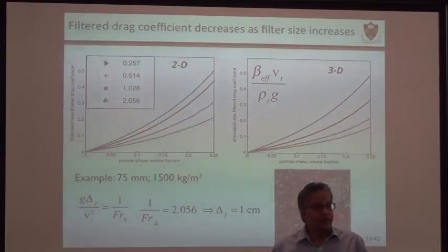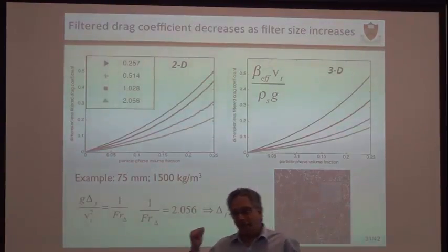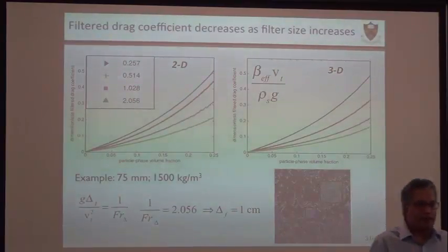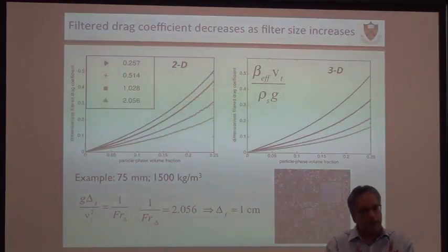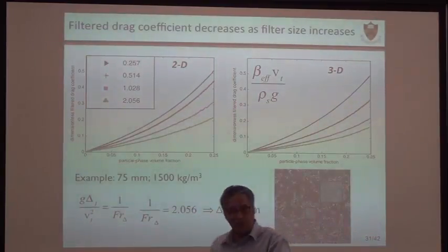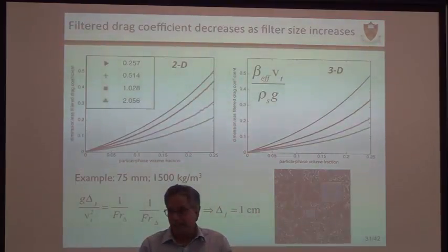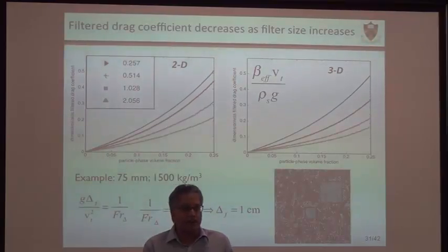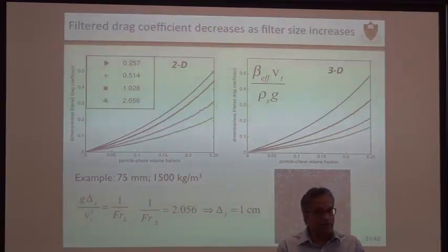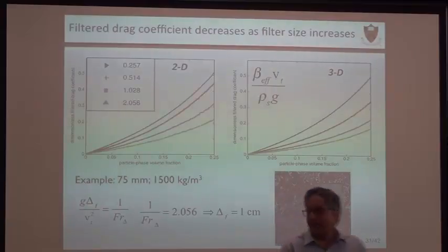That's what all the CFDs were predicting. But all the industrial reactors are operating at 3 times the terminal velocity, and they're perfectly fine. So you have no hope of ever doing that. The reason why there's no hope is that they're all pretty large grids, and they are grossly overestimating the interaction. You are grossly overestimating the interaction, but you're not putting in a fine enough grid to resolve this structure, and that's why you're getting nonsensical results, which is earning a bad name for CFD. So all these results are trying to fix those problems by correcting these directions.